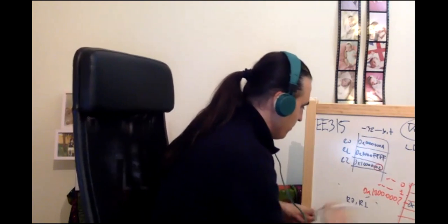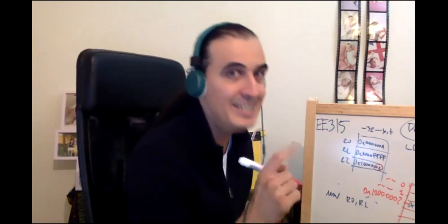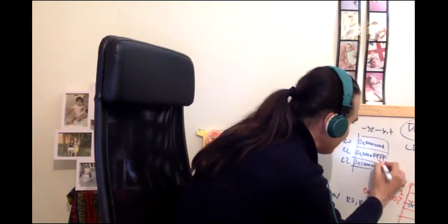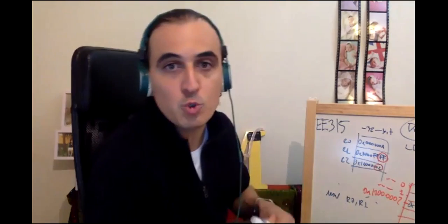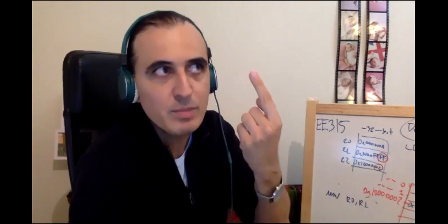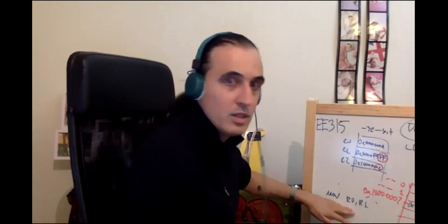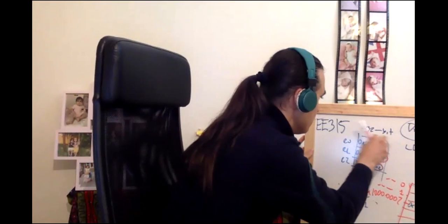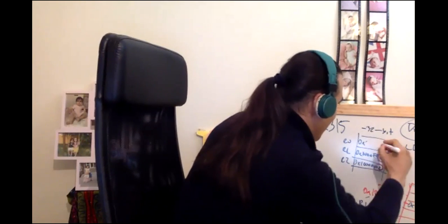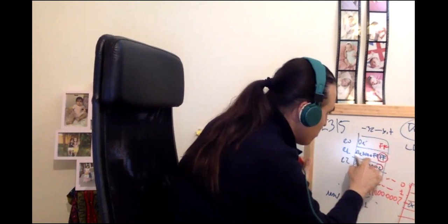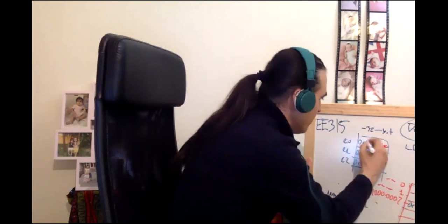However, if this is move, it is only doing the operation in the least significant 8 bits. Because 8 bits is 2 nibbles, guys, and each nibble is 4 bits. So if I do this operation, it is going to write FF, but it's not going to write these other ones, and by default, it's going to write 0, 0, 0. So move is like an 8-bit version of LDR.